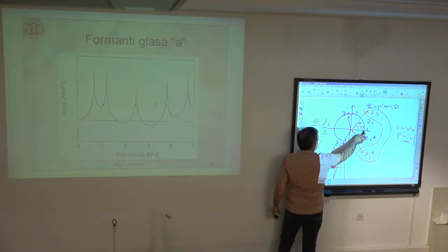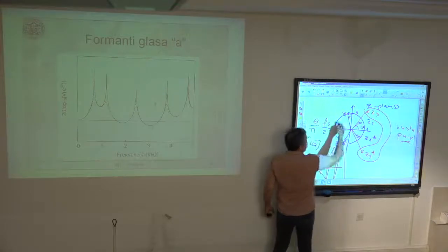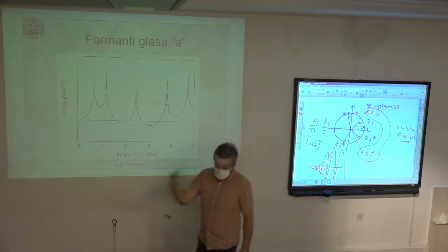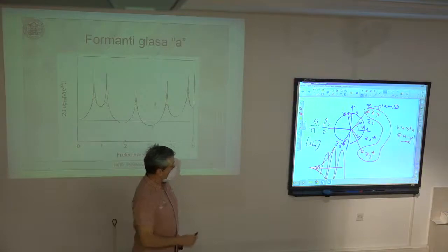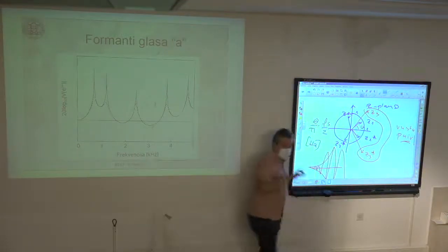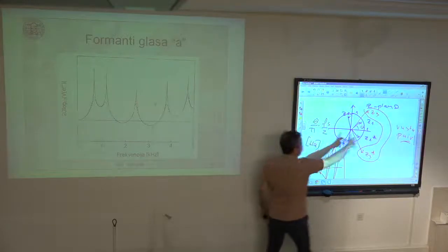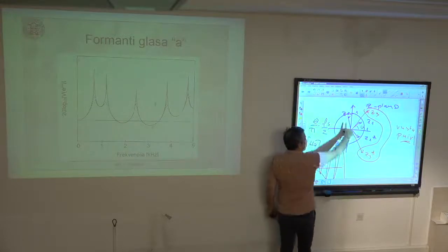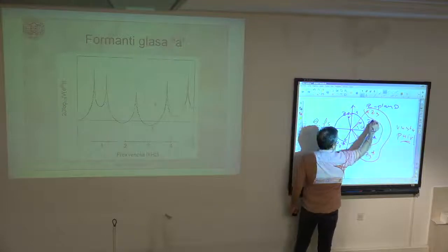If I go from 0 up to 1/2 of the sampling rate along this unit circle, I simply test how the vocal tract affects the output amplitude. As I come close to the pair of poles, this amplitude increases. Then I come close to the next conjugate pair, and again the amplitude increases. So something like this.